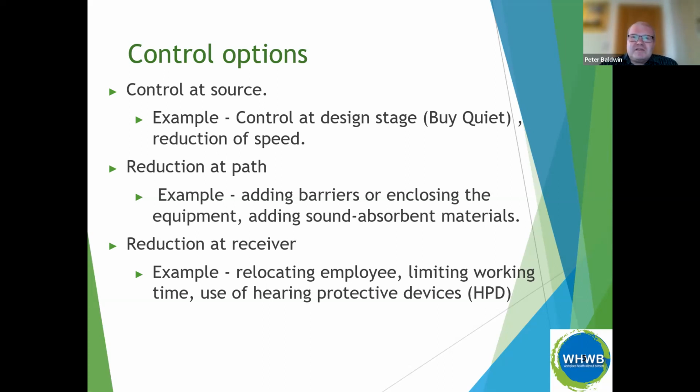Looking at the reduction at the path here, as I said, adding barriers. So basically put a wall up of some description, and that could be quite effective if the worker's behind the wall. And when I say wall, it might be just a mobile piece of what you might get in an office, something of that ilk, just a little barrier you put up between desks. That's quite effective at reducing that low-level noise in offices. And a similar sort of theory can be applied in a factory or other noisy processes.